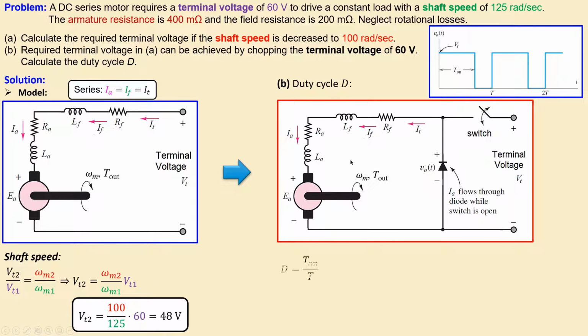Okay. Then the duty cycle is given by this expression, which you see: the duty cycle expression is the time on over the period. So what is the total time that the switch is on, so actually closed, over the total period of this signal? And that is then related to the terminal voltage we require over the terminal voltage we actually apply across these two elements.